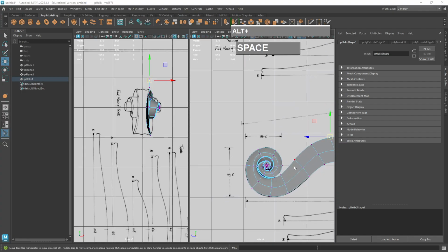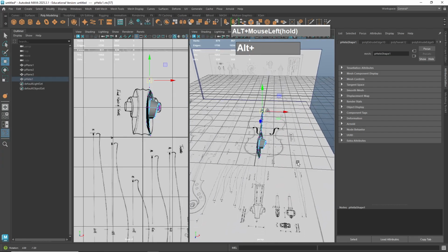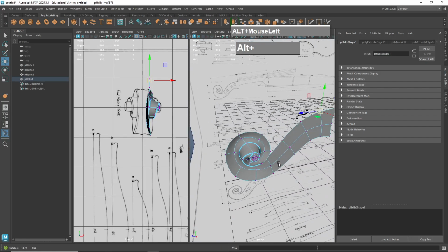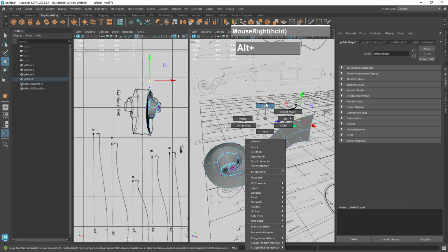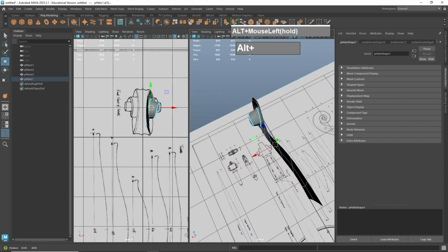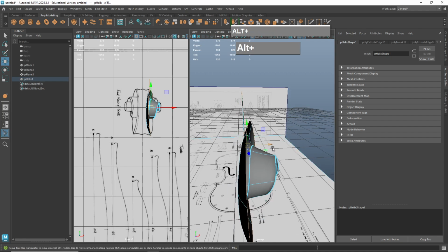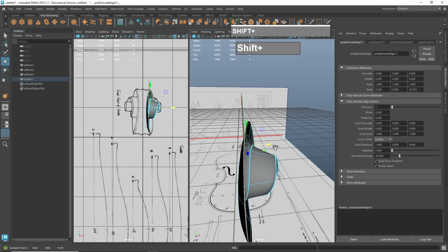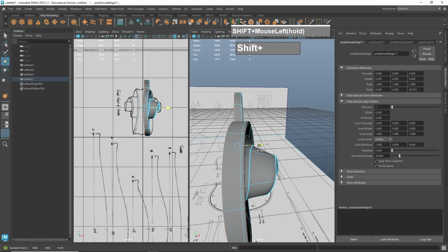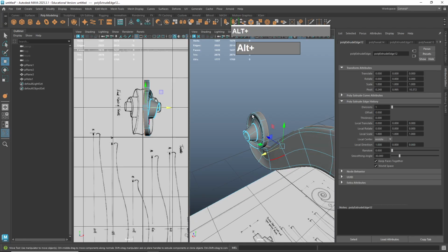Alright, so now we will have to create the thickness of this neck here. So I will select the open edge here by double clicking on it. So this entire edge is now selected. Then I'm going to extrude out one tiny section first, holding down the shift and extrude out one tiny section like that. Then after that, holding down shift again and extrude another one. So this is in order for us to hold the hard edge around here.